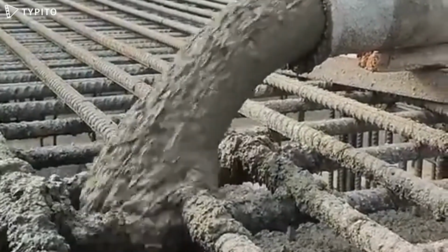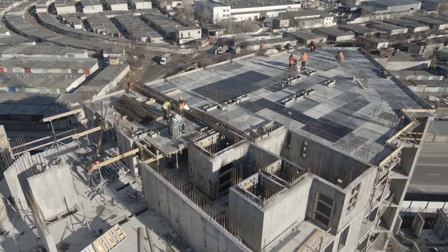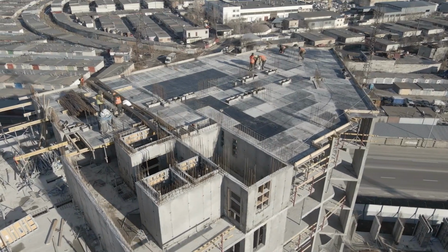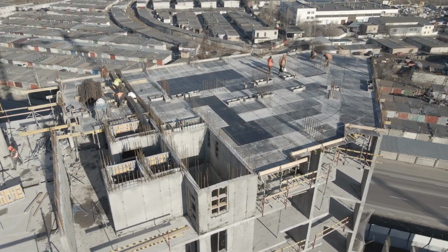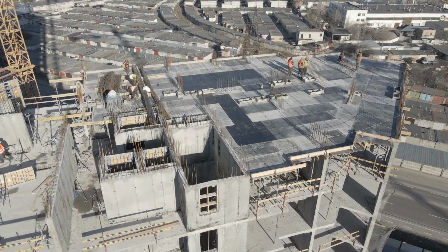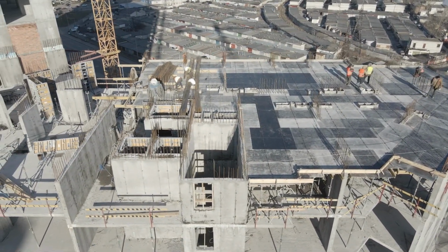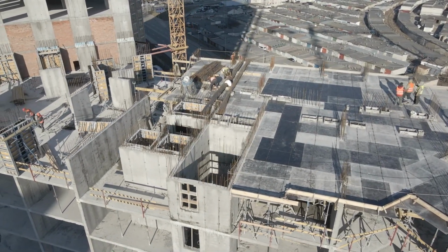Before pouring concrete to slab, you must first place the formwork. Formwork for slab. Formwork for slabs, also known as decking or form decking, is used to support and contain the concrete during the construction of horizontal slabs. Here are the key components and steps involved.